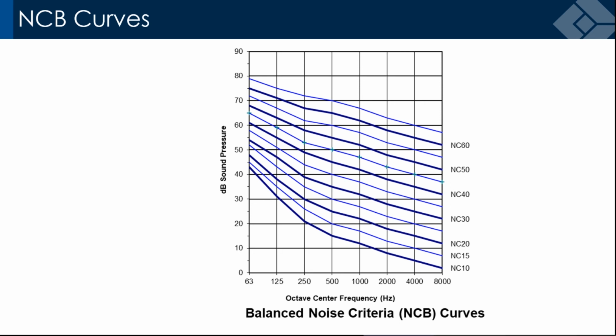So there are a few different ways to calculate noise levels. A lot of our people use an app from Vibroacoustics or just have Vibroacoustics do the calculations. And I think that's a perfectly good method because their policy is that if they're put number one on the schedule, they'll guarantee the performance of the silencer. Also, we have the spreadsheet that I developed, which will do almost anything if you can figure out how the mind of Jeff Bolt works and work through the spreadsheet. But it will calculate unweighted dB, dBA, NC, RC Mark II, outdoor property noise. That's actually the fastest of all the acoustical calculations to make in the world, is doing outdoor property noise calculations.